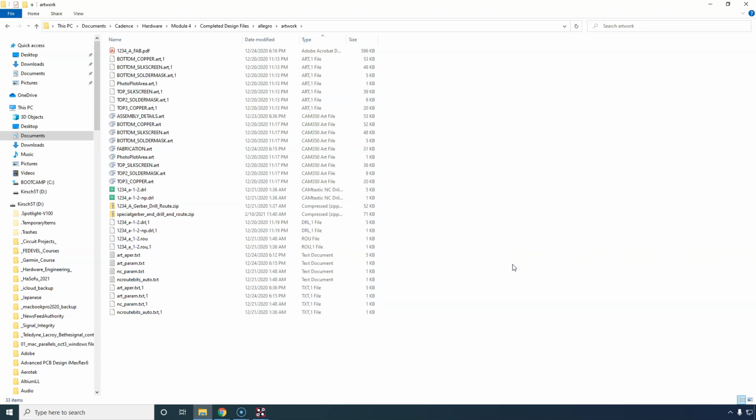I hope this video has been very helpful to you because I spent a long time working on it. It's been 46 minutes, but this is generally how long it might take for generating Gerber files. I recommend that if you have a Gerber viewer, especially a free one, get a free Gerber viewer and look at your Gerber files to check them yourself as well. Because when you submit it and you're waiting on feedback from the manufacturer or the DFM tool, you want to see for yourself why it might have errors. Be able to assess that. That's how you learn.